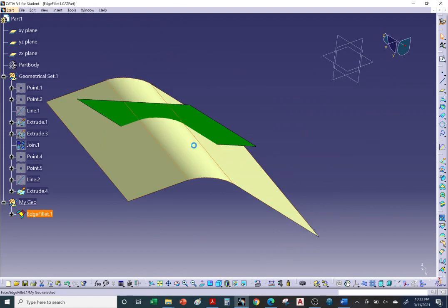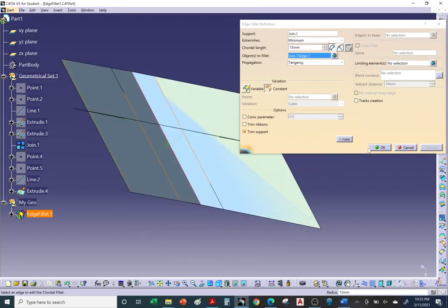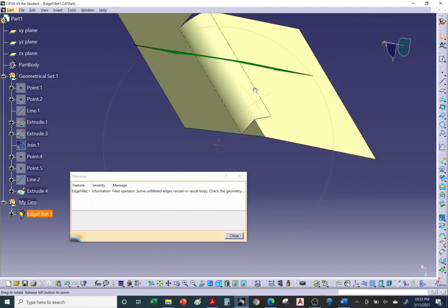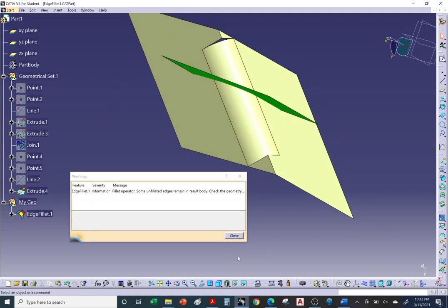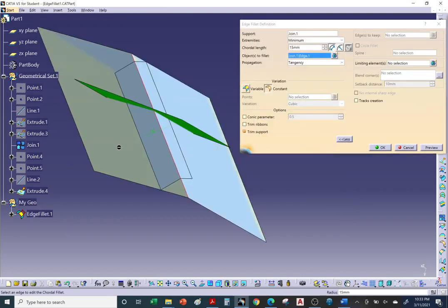And just like shape fillet, you can also go with minimum fillet. And preview. Let me hit OK to show you what a minimum fillet looks like. So that's the minimum amount as far as the fillet. The shortest fillet it can give you between the surfaces that are joined, and we're filleting the edge.